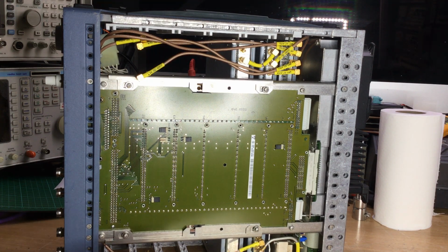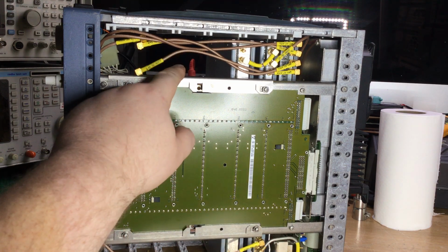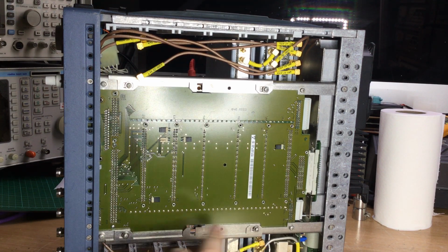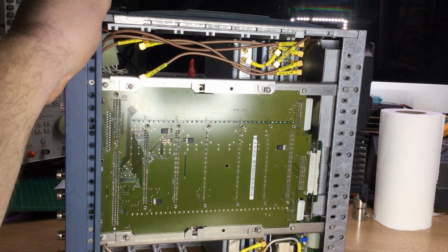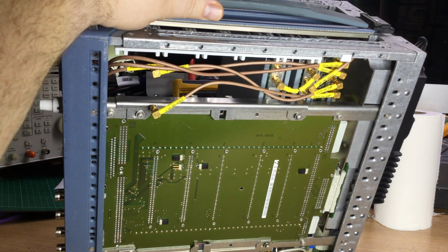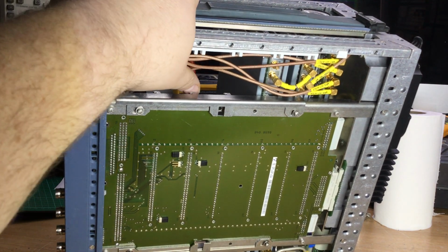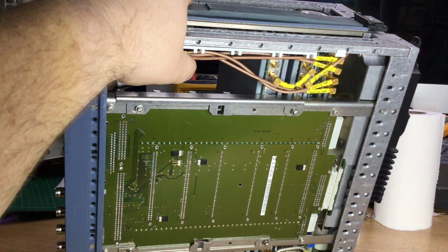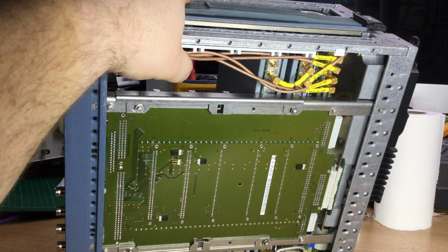So firstly, how you get the modules out on these CMS series of radio tests, it doesn't matter what version of Rohde Schwarz radio test set you've got, they're all the same. There's these brackets here, and each bracket is held with two screws. So all you do is you just slacken the screws off, and right at the top of the bracket, you might just be able to see it if I just tilt the test set in the right sort of way. You can see those hooks on the top there, these little hooks, and they hook into the modules to prevent them from coming loose and dropping off the board.